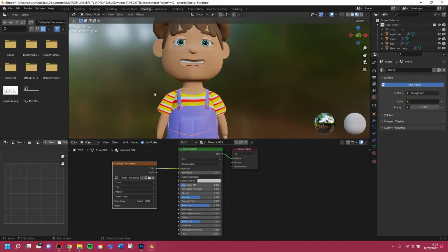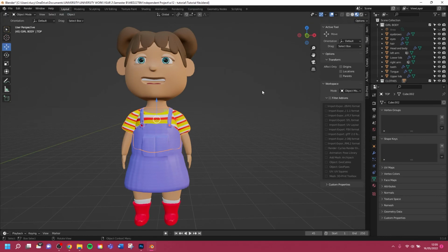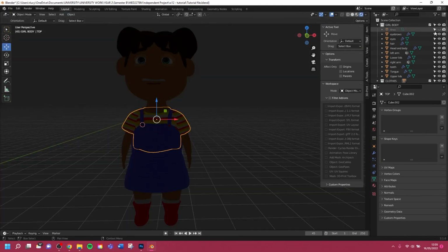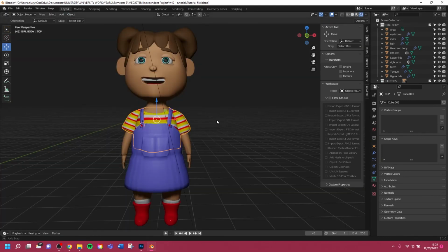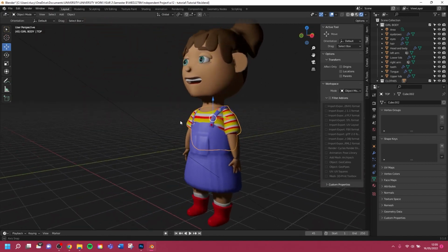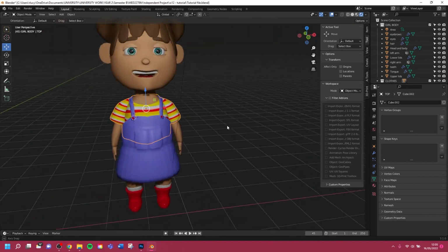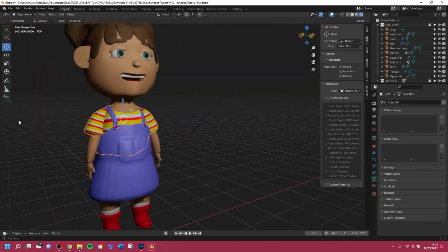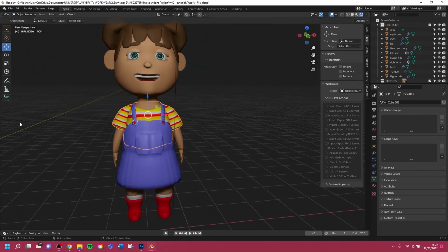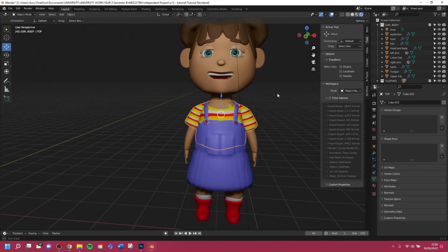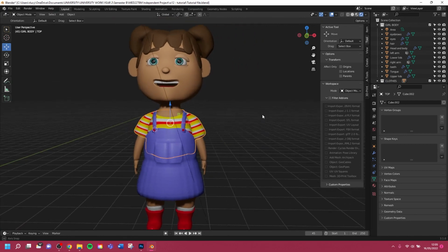Finally, we should look through our render mode just to ensure that everything looks as we want it to. So head to Layout, go to Render mode and add in a light source. As you can see, the top looks like it fits nicely and the image is nicely wrapped around. Following this tutorial, you have managed to accurately add an image texture onto a mesh and wrap it round in order for it to fit nicely.